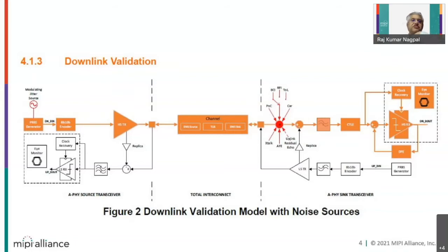These are static noises. Another category of noises are EMI, RFI, RF ingress, and large transient noises. These are not always present simultaneously, and it is expected in the simulations that only one of these noise sources is present at one moment of time. So you validate your system model taking each one of these one at a time, and you validate your static noises as always present. This is the kind of integrated noise environment you have to consider in your system model.